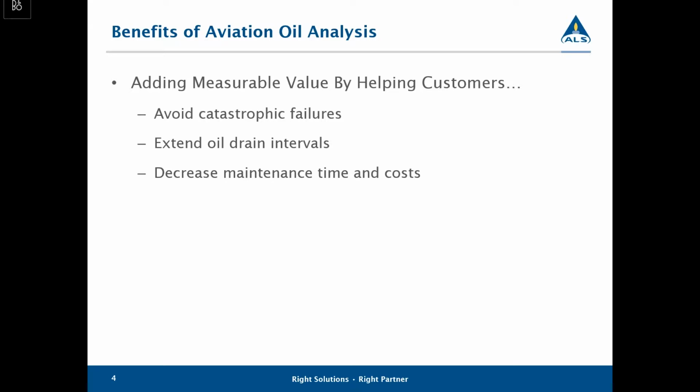It also helps decrease maintenance time and costs. A lot of times with oil analysis, you're able to determine the source of that wear. And so instead of assuming what the problem might be and taking some maintenance actions and then hoping that that's going to fix the issue, oil analysis will help determine where that might be coming from. So understanding what wear metals are appearing on that report, you might be able to determine that it's coming from the piston area of the engine. It could be an accessory drive that's wearing, and you'll be able to pinpoint that problem and maintain it correctly. And then it also reduces costs as well.